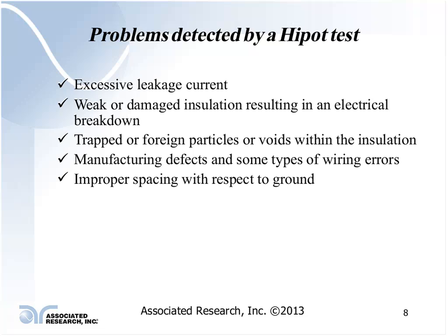Okay, so it's operating from essentially a three-prong plug, and it's grounded. If there's excessive leakage current, that leakage current should be safely routed to earth and not through the operator.